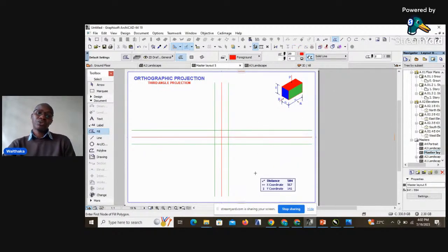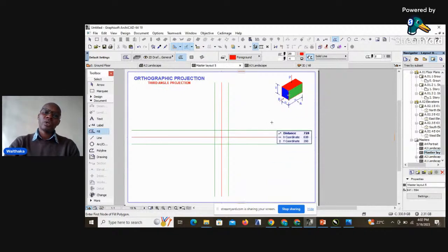We use the same Cartesian plane as we used in first angle, but now the views will change a little bit. So our plan in relation to the end view will be our front view in relationship to the end view. We'll place it in this quadrant.